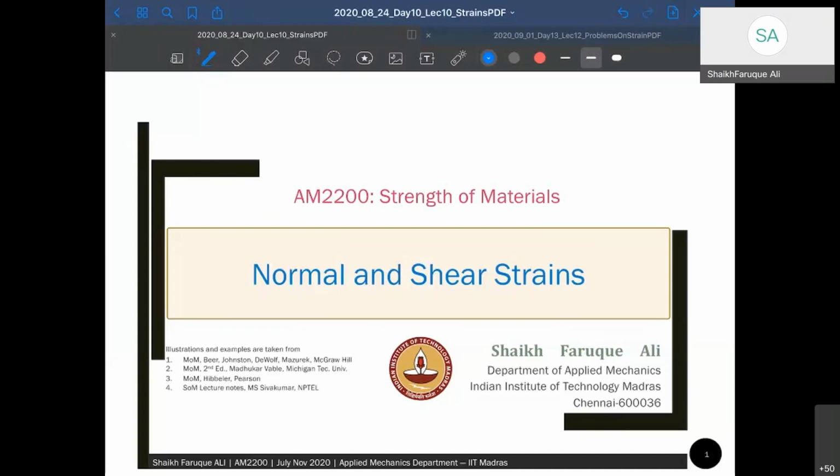And these two points, the deformation or the relative motion between these two points can be calculated, and that's also one of the measures in solid mechanics that we need to be learning. Okay, and that's called strain. So today our objective is to understand what is a normal strain and what is a shear strain. Tomorrow we will extend this understanding to how to calculate strains, right? Normal and shear strains on a material point, right? And the next class we will solve a few problems, and with that strains will be.